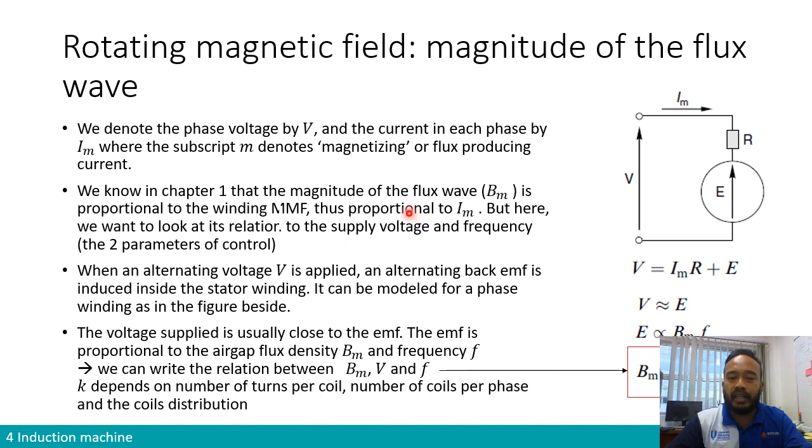But here, we are not going to look into the current. What interests us is the relation of the flux density or flux to the voltage and frequency. Because in an induction machine, we are not going to be able to control the current, because the current depends on the load. But what we are going to be able to control is the voltage supply.